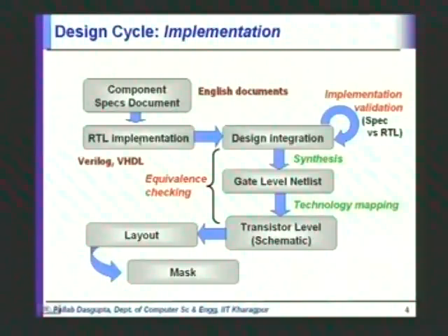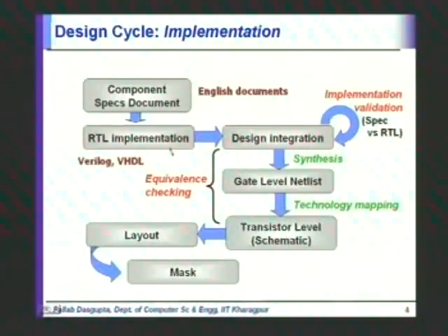The unit level is the smallest granularity modules, in other words, modules which typically will not have any other modules instantiated within them. So it starts from coding those unit level modules, then you plug together the unit level modules to define a larger block, then you take a set of blocks and define another larger block, and this is how the design coding takes place.